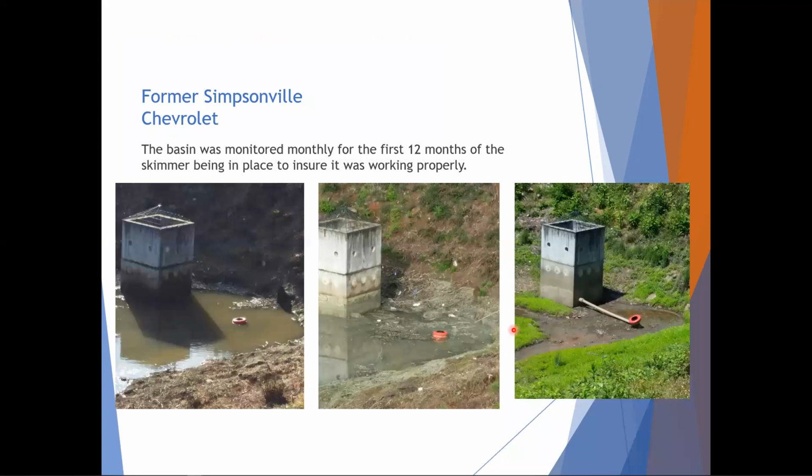So we actually went in and modified the design of the basin. They were going to have to clean the entire basin out, which would have cost probably $75,000 to $100,000 to get in and do that work. But this was one of those rare basins that's actually a little bit oversized and had some extra volume. So we closed in these low orifices. We put in some orifices a little bit higher, and we put in a skimmer as the low flow orifice instead of the 2-inch orifice that was below.